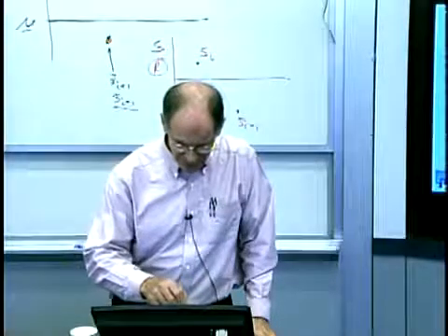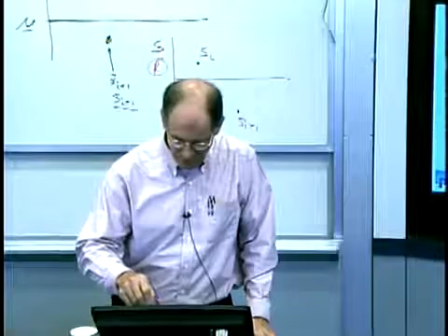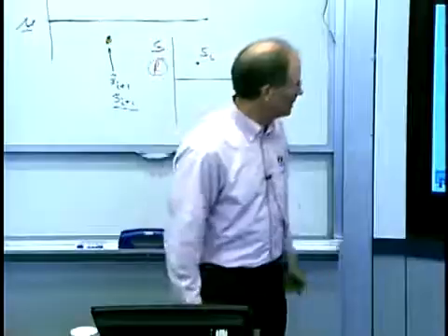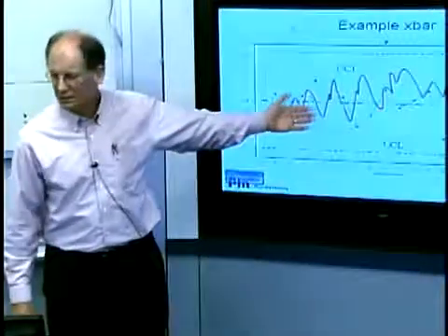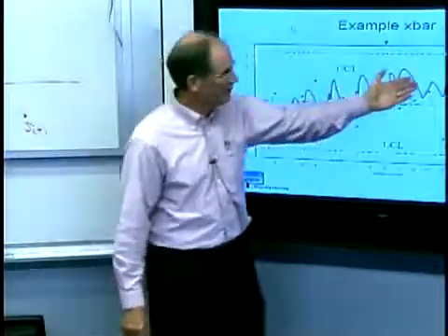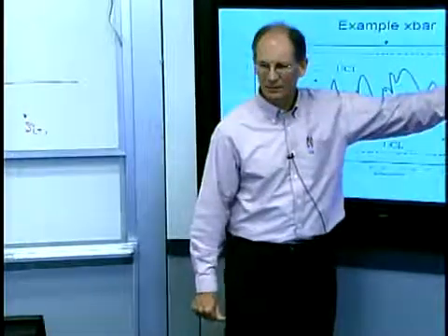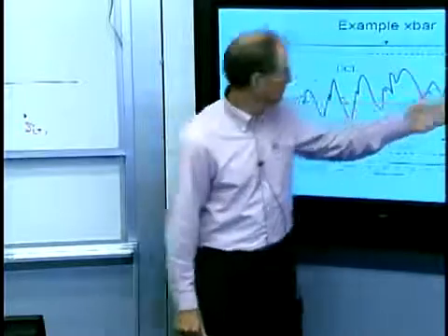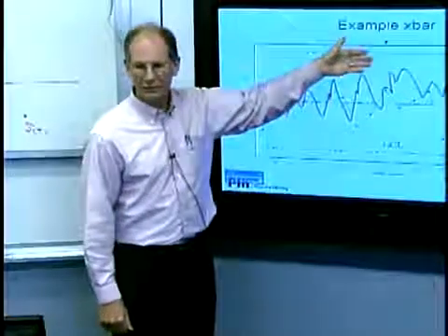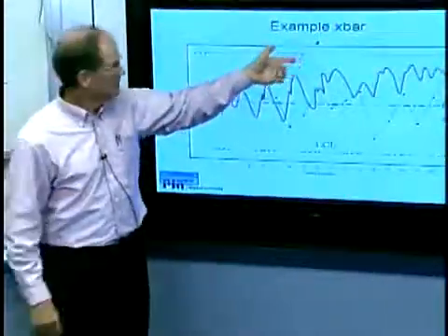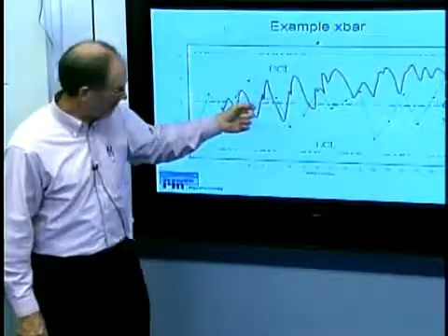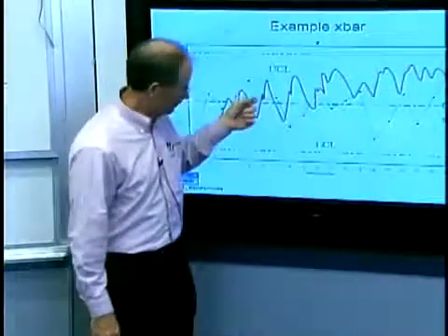But what if it was doing this? Okay? And you eyeball that, and would you say, is anything wrong with this process? Yeah, look, it's trending up like crazy. When did that trend begin? Like maybe here? Now, if all I do is have an alarm when I cross over this upper limit, can you see that something's been wrong for a long time?